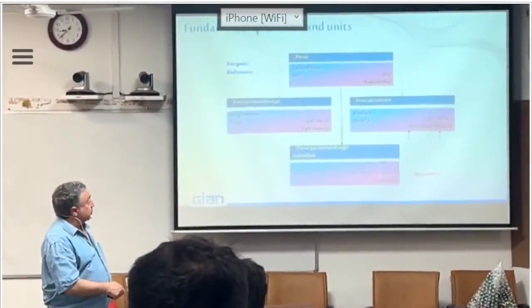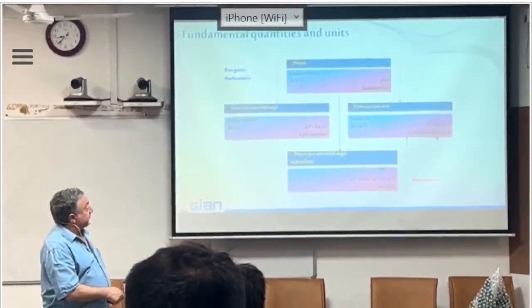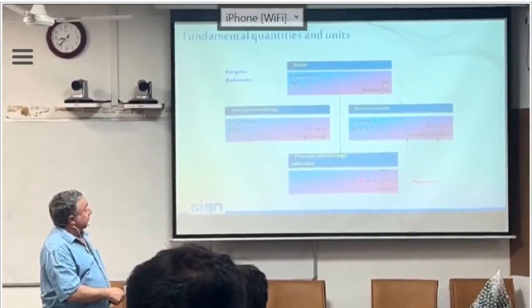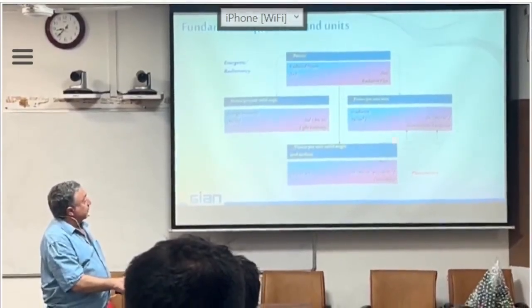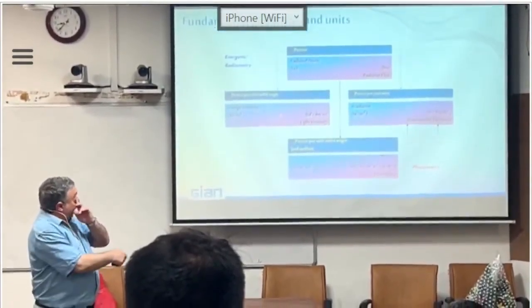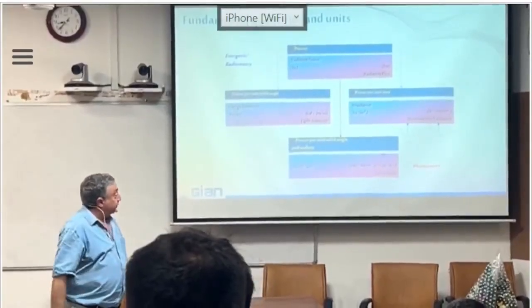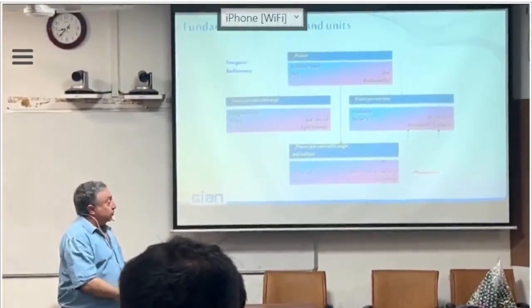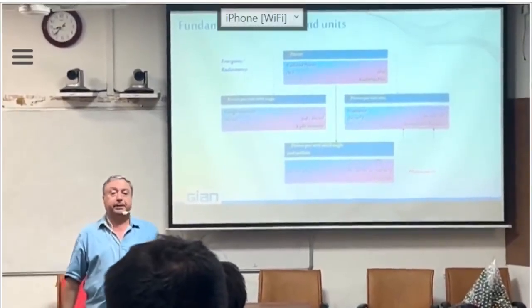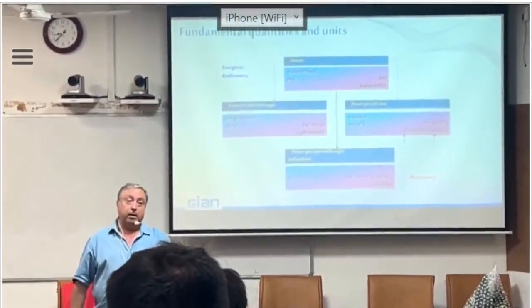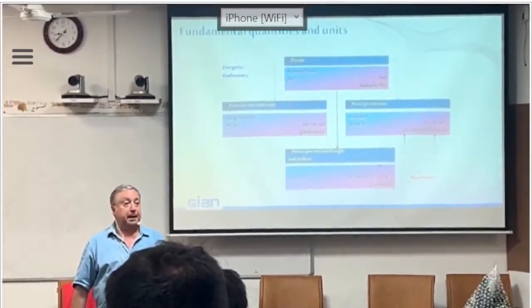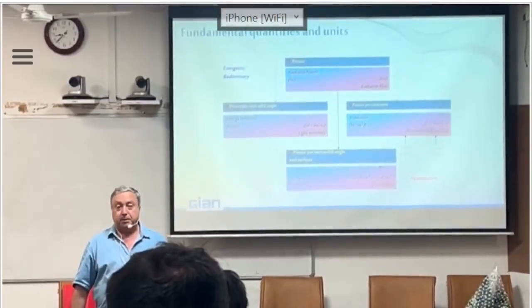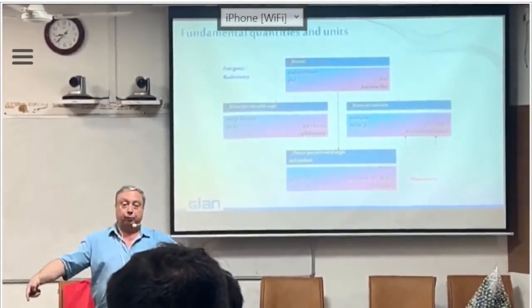It is measured in lumens per square meter and steradian, but lumens per square meter, per steradian, sorry, is the candela, is candela per square meter, and in European literature, you can find also the unit nit, NIT, or if you go to American, you speak about foot candelas. That means candelas per square foot, okay?